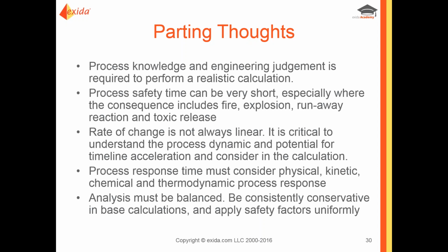Let's see, I assume we should consider the T90 time of the thermal wells within the total SIF response time, isn't it? Yes, if you have any kind of delays with your process signals, like if you're doing some kind of analytical signal, there may be a little bit of a lag while the analysis is occurring, or there may be a cycling delay, a polling time associated with that input sensor.